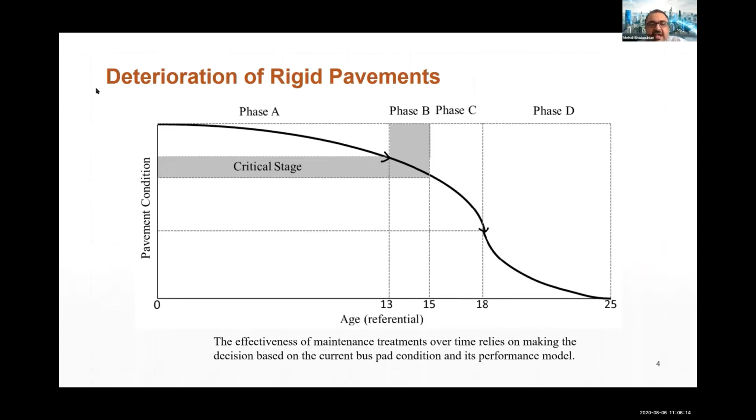In phase C, after the accelerated phase, the optimal intervention time passes, and the more the intervention is delayed, the greater the damage and the higher the repair cost. The damage that occurred in the basic structure of the road must be repaired, which means demolishing and lifting the damaged parts, replacing the components with new ones, and then reinforcing the road surfaces, which is mainly costly. This group of activities is frequently named structural maintenance or rehabilitation.